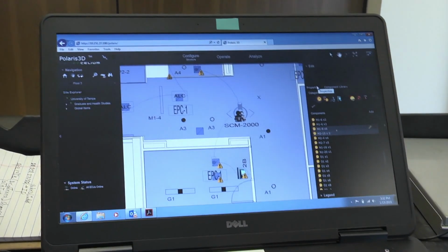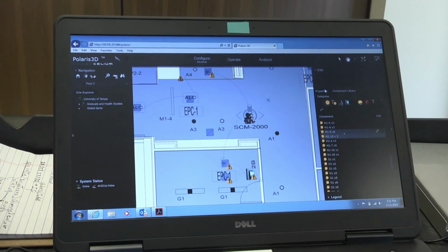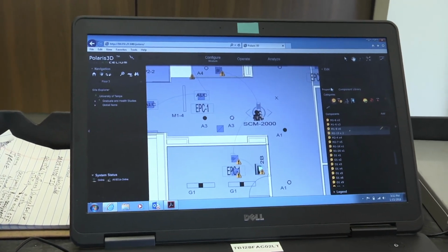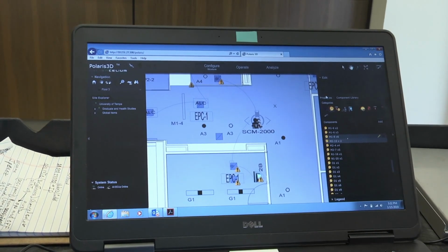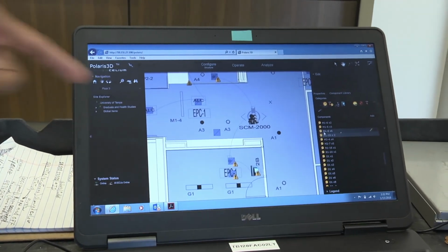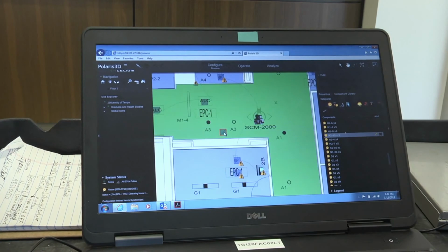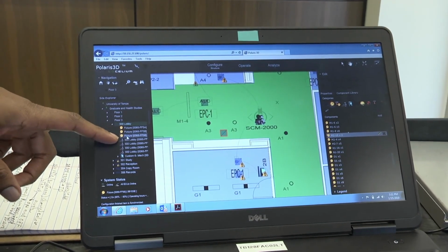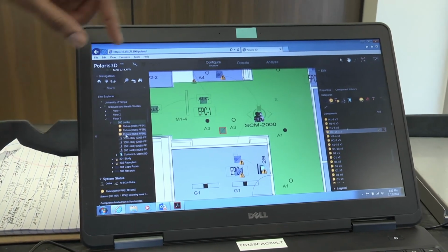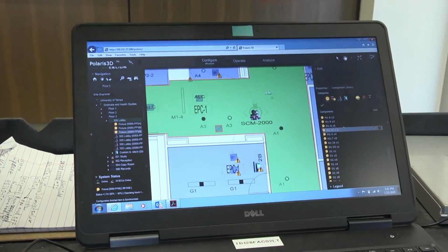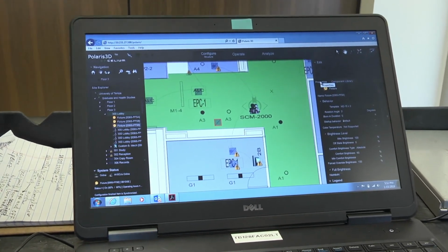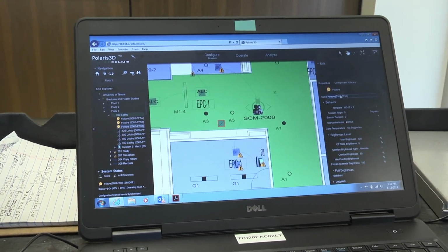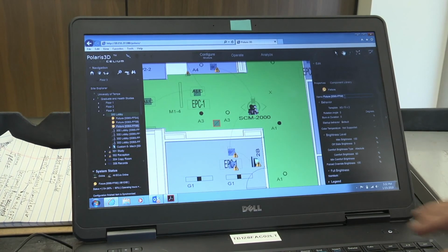Okay, so in this section, you created the actual fixture template, but we're going to go a step further into showing you how you can actually name the templates so it makes sense to you on the floor plan. If you select the actual fixture template on the floor plan, it just gives you a generic fixture. Everything is going to give you a generic fixture. So go to the properties section of that right now, and where it says fixture, this whole thing here, erase all of that. Select it and hit delete, and give it a name.